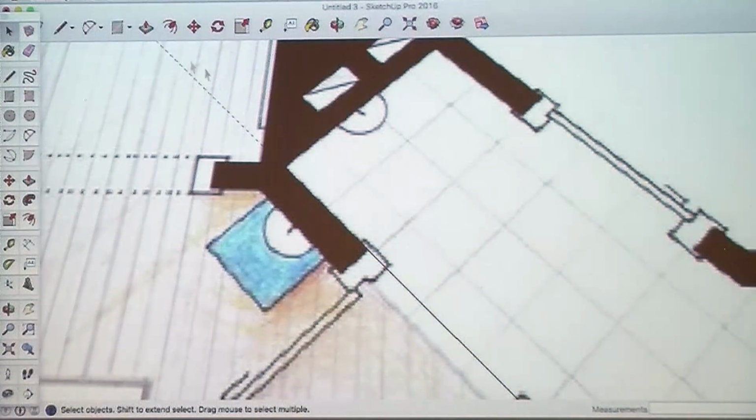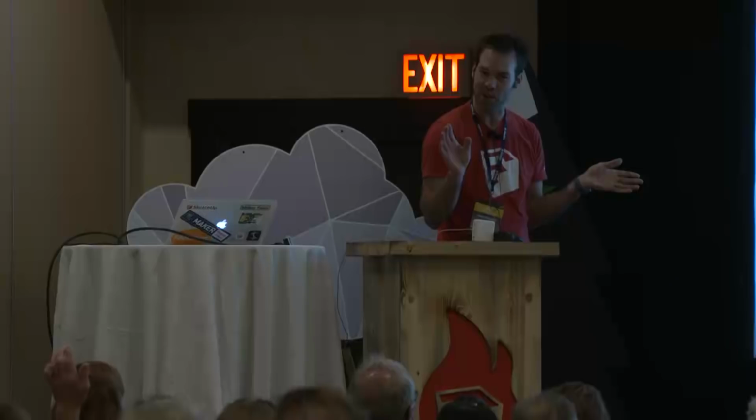So what I'll do is take my pencil tool and click on this line, and I just kind of point at the line I made before, which is kind of telling SketchUp, hey, I want to reference this line with the next line that I'm making. So if I do that, and I move up here, see how it turns purple? Has anyone ever seen that before and not really understood what that is?